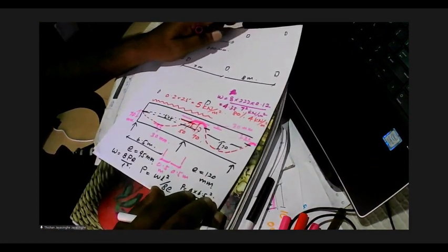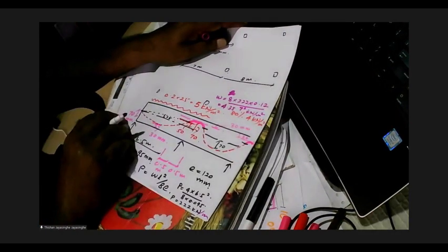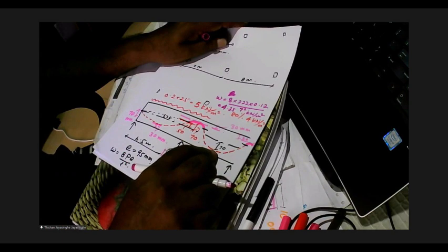So can you see why I didn't go for 90%? I could have gone for 90%, but I have gone for 80%. So I balanced 4 kilonewtons and found the pre-stress has to be about 222 kilonewtons per meter. And then I found how much I am balancing over this distance. So I am balancing 4.35 kilonewtons per meter square.